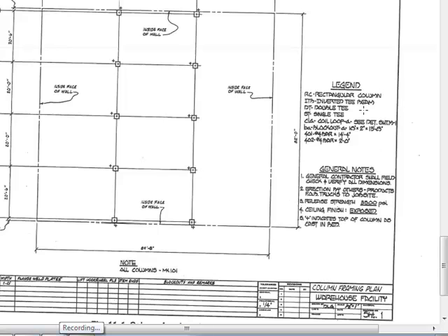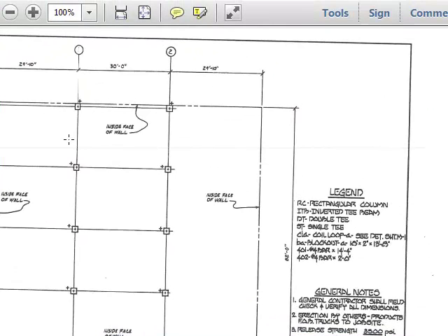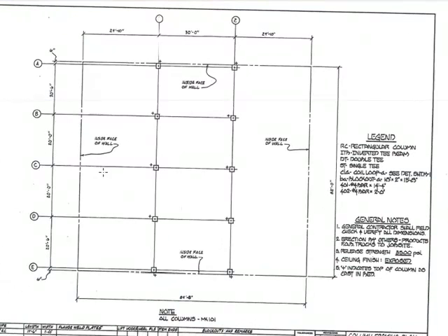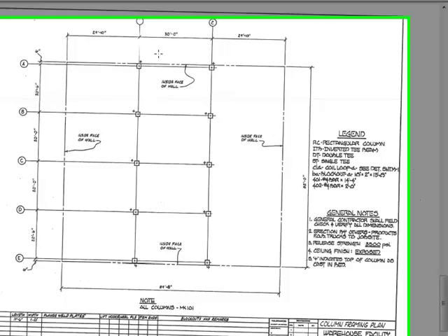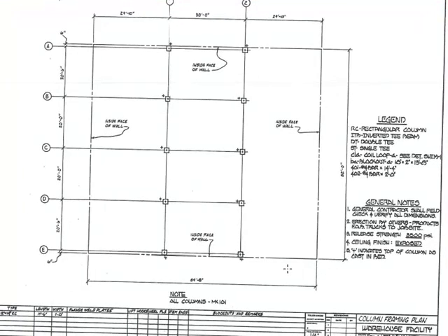In a column framing plan, of course, you have the columns, and that's what you're trying to highlight, and this is based on whatever information was given them. They've drawn the inside face of the wall, which would be the precast concrete wall that you'll see in a minute. Then they have these interior columns.